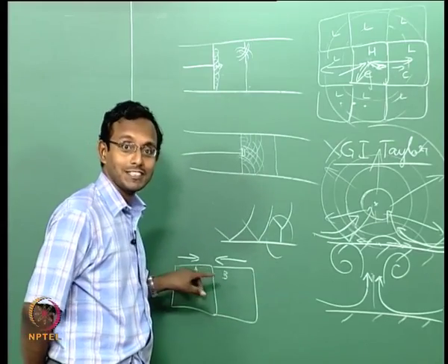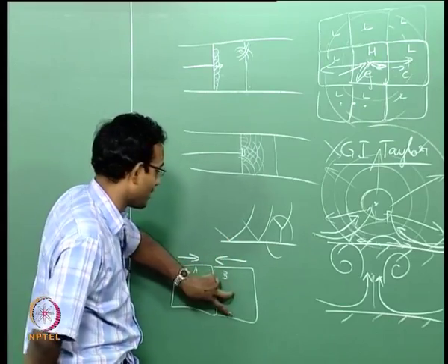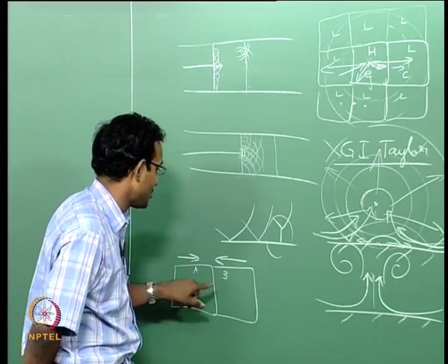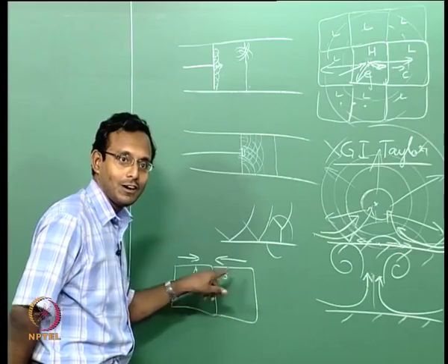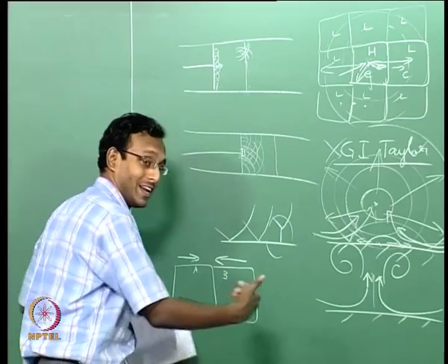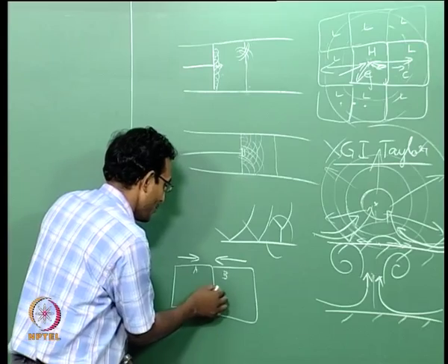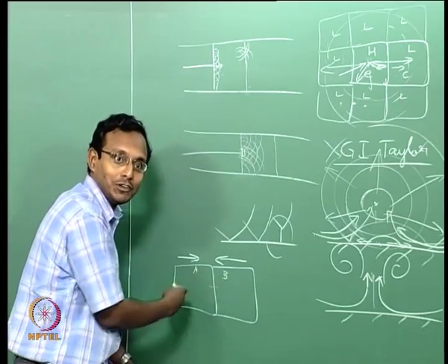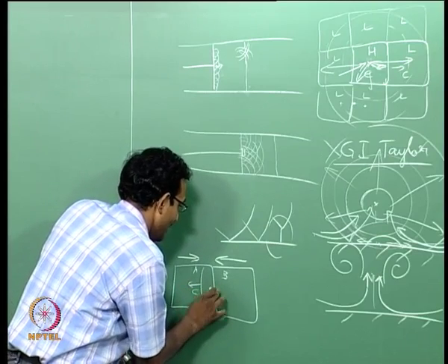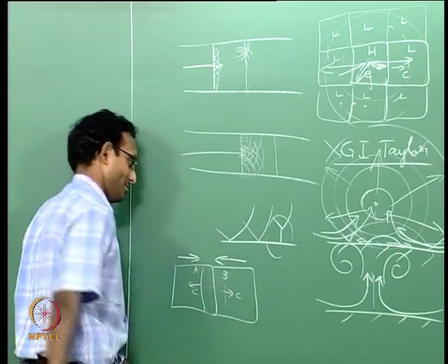Finally they should move with the center of mass velocity, of course, and the relative velocity between these two is what I am considering here. If I consider only that, one fluid element has relative velocity normal to its surface on the other fluid element. If that is the case, then they are colliding against each other. It is as if this surface is moving into this, equivalent to a wall moving into a fluid element. I am going to create compression waves going this way, and similarly this is going into that, so this will also have a compression wave going this side.